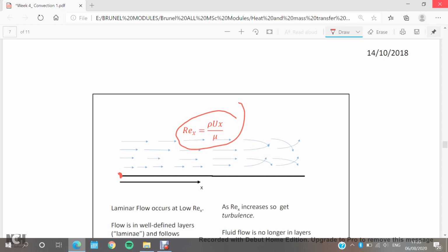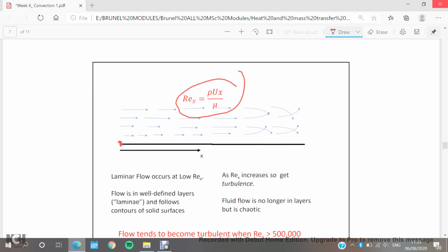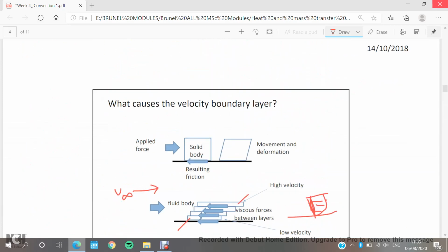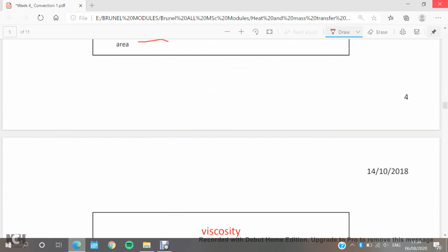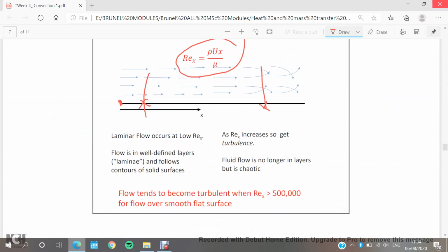Here we call it Reynolds number with respect to x, which means local Reynolds number. If I calculate at x in this point, I have a Reynolds number completely different than x in here. Okay, why? Because when x is increasing, the Reynolds number is increasing. If we go back in here, we'll understand this idea. Like in a small x, Reynolds number is small, which means laminar. But when x is increasing, we will have turbulent flow, which is a higher Reynolds number. Okay, great.